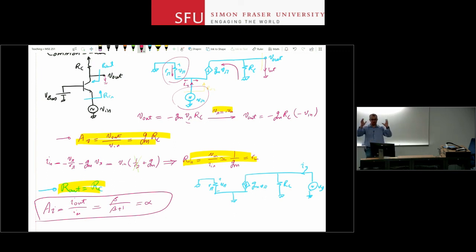If you can reduce a complex circuit to one of these known stages or a combination of them, then you can reduce that stage to just 1 input resistance, 1 output resistance, and 1 gain value, and simplify your circuit analysis. Very, very helpful, especially when you have a multi-stage amplifier.